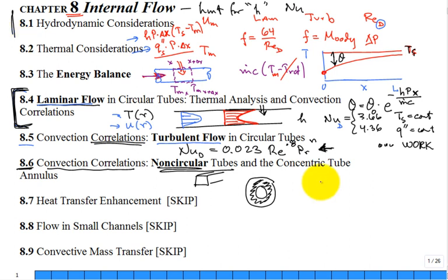You would use D subscript H. What's D subscript H? From fluid mechanics, hydraulic diameter. And then once you have an estimate, kind of an equivalent diameter for the system, then you can go and use your traditional correlations. Now, they do a better job if you have laminar flow.